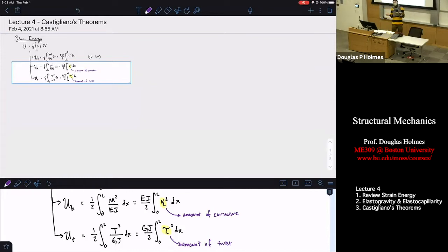There's one more I didn't give you. I'll give it to you now. It tends to contribute less to the energy stored in an elastic body, except in extreme circumstances. Extreme circumstances means thinking about 1D objects. It would be a really short beam or, well, I don't know what the opposite of slender is. Slender would be if one dimension is really thin compared to its other lengths. If it's a really stout, short beam, then you're going to store some energy in transverse shearing.